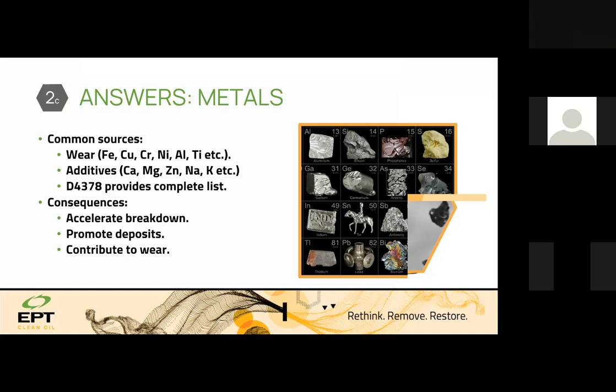One of the things I do with additives, for example, if there is a turbine oil, and in turbine oil you don't find zinc, and then I find zinc in the used turbine oil sample, when I do analysis I understand that there was a wrong top-up of hydraulic oil in the plant, or they were using the same jar or same pump where they are transferring the lubricants and so on. So if there was no element in that new oil and now it is being added, you can know by oil analysis